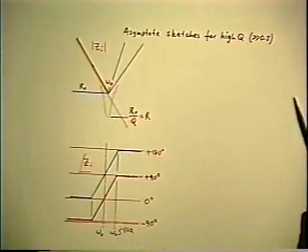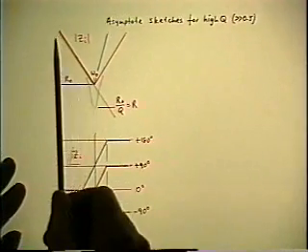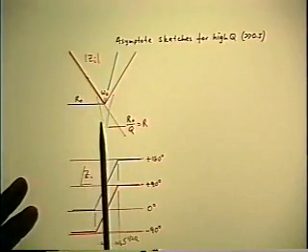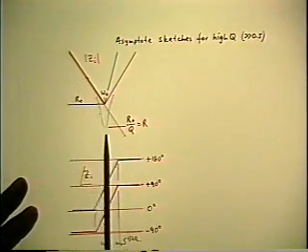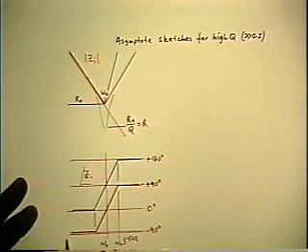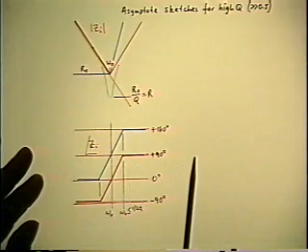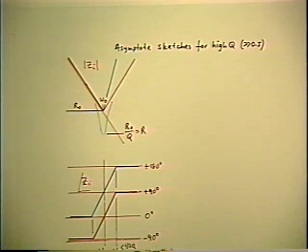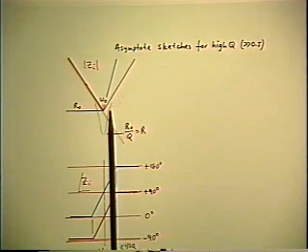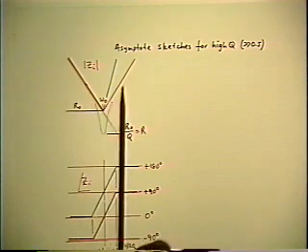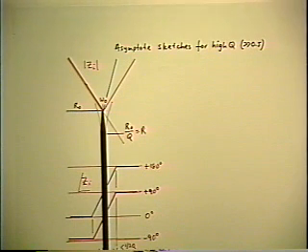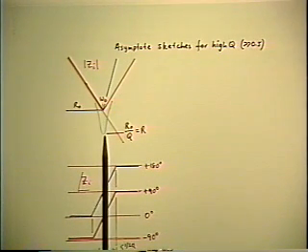So the input impedance of the LC filter follows the red asymptotes, and you see it's the typical series resonance. The impedance goes to a minimum and comes back up, and the phase goes from minus 90 through 0 to plus 90. That's expected, that's familiar, but of course notice an additional useful piece of information here. The asymptotes intersect at the normalizing resistance R0, the characteristic resistance of the L and the C. The value of Q determines what the actual minimum is.